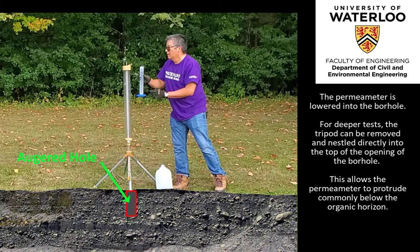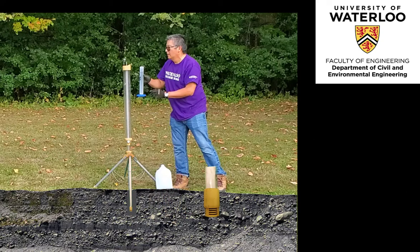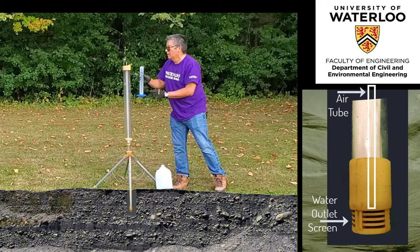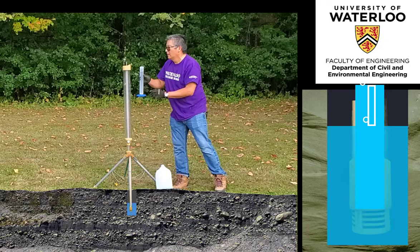The support tube of the permeameter is lowered into the borehole with the reservoir filled. At the base of the support tube, there is a water outlet screen, shown here in yellow, which is required to rest at the base of the borehole. The air tube, which is initially resting at the base of the support tube at the bottom of the screened water outlet, is then raised to the desired hydraulic head, such as 5, 10, 15, or 20 centimeters.